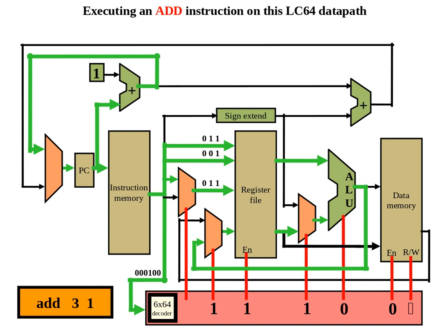You can think of it as where the path begins. It's up to you, but this may help. So the instruction comes from instruction memory. It's going to forward 3 to the register file and 1 to the register file, which will output the contents of register 3 and the contents of register 1 down here.